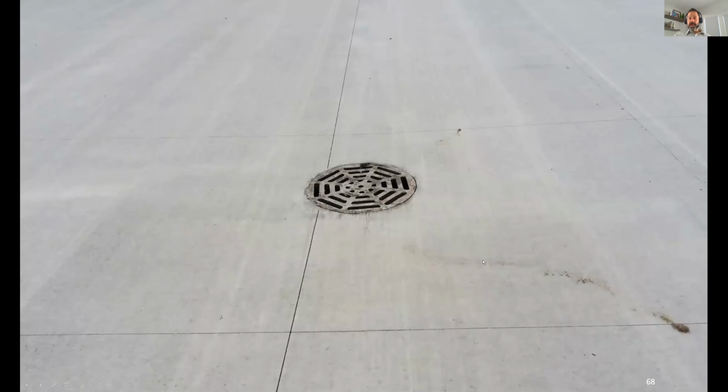Here's one where they didn't dog leg. I like to go back a foot or two, maybe 3 foot, stop that standard joint in its normal straight location, and dog leg into that casting. Just if you're a saw guy, look at that center right there, that casting, and wherever you start, point the saw right at the center. If you point it at the center, you'll be perpendicular at the edge. So this is something I would have rather seen.